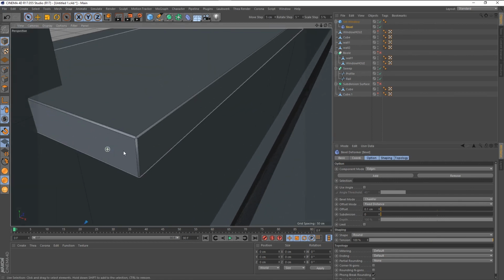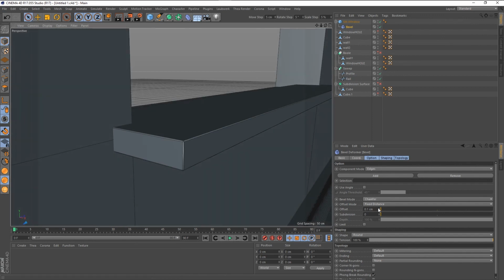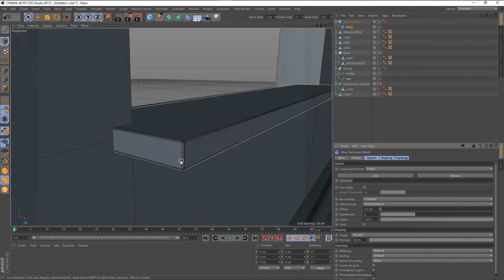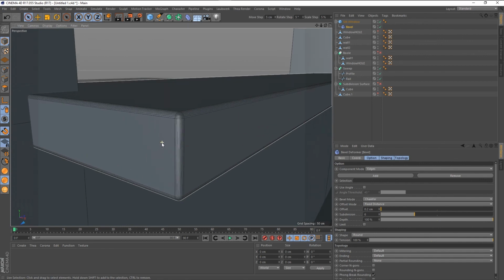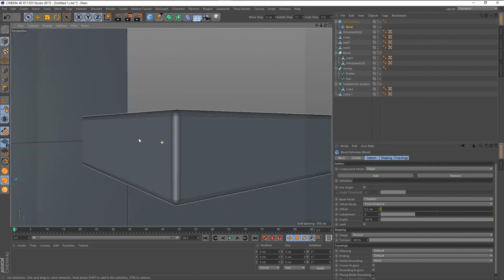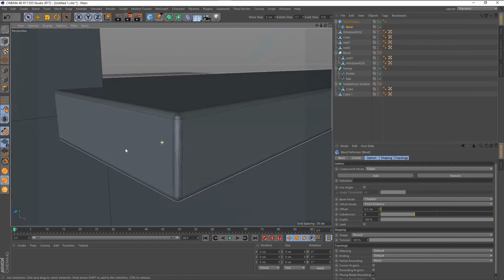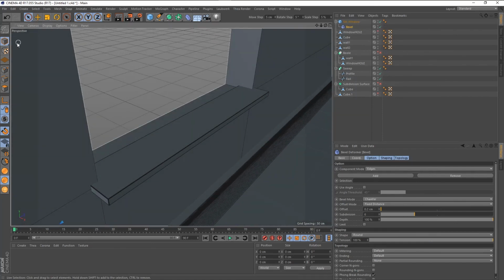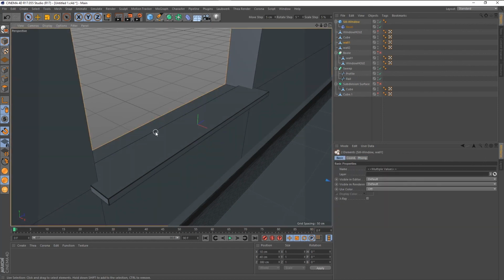And then the bevel, if I choose that, I can change the offset to be 0.1. And we can change the number of segments. Let's say 0.2. There we go. And we can change the subdivisions to, I like 6, but even 12 is even better. But you can see 6 gives you a very nice, smooth bevel. So we still have a fully quad model. And that's working on an object that is a parametric object.